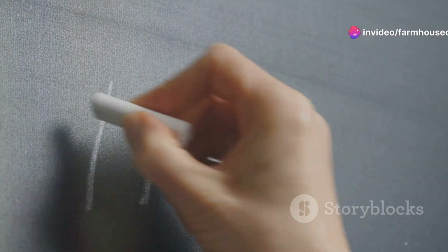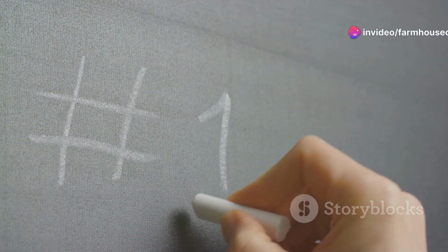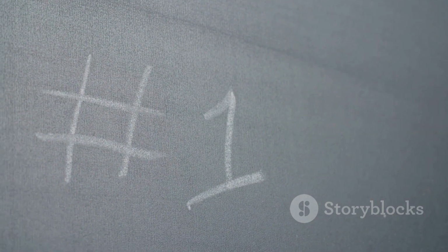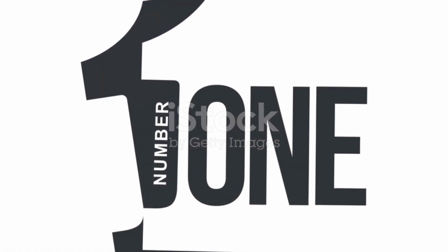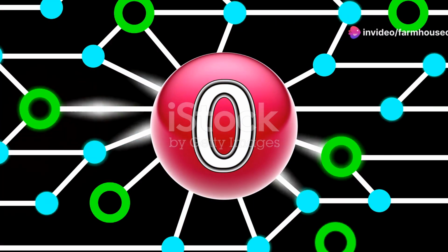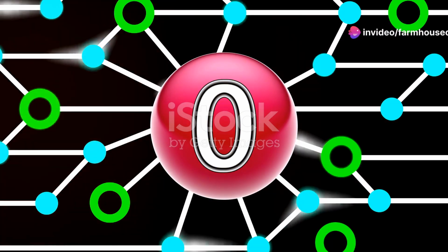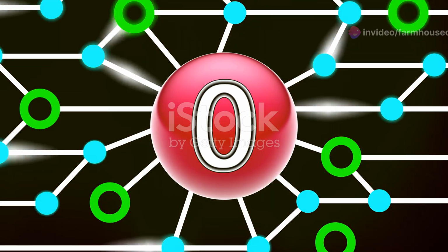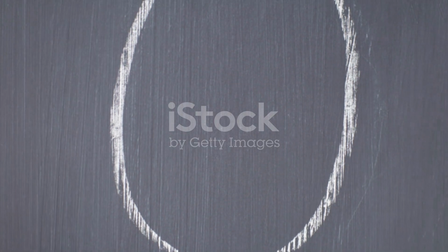If an input combination results in a 1 output, we place a 1 in the corresponding cell. This indicates that the specific combination of variables produces a true result in the Boolean function. If it results in a 0 output, we either leave the cell blank or fill it with a 0. This step is equally important as it helps in identifying which combinations do not satisfy the Boolean function.